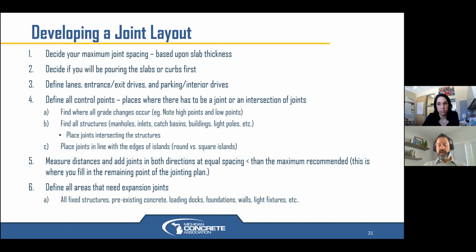Any place you have one of these structures, a penetration through the pavement, a gapped out area, that is a small gapped out area, I should say, that is an area of stress concentration that will cause shrinkage cracking to start at that place before it goes anywhere else. So you really need to pay attention to your jointing if it's not a continuous ribbon of concrete.